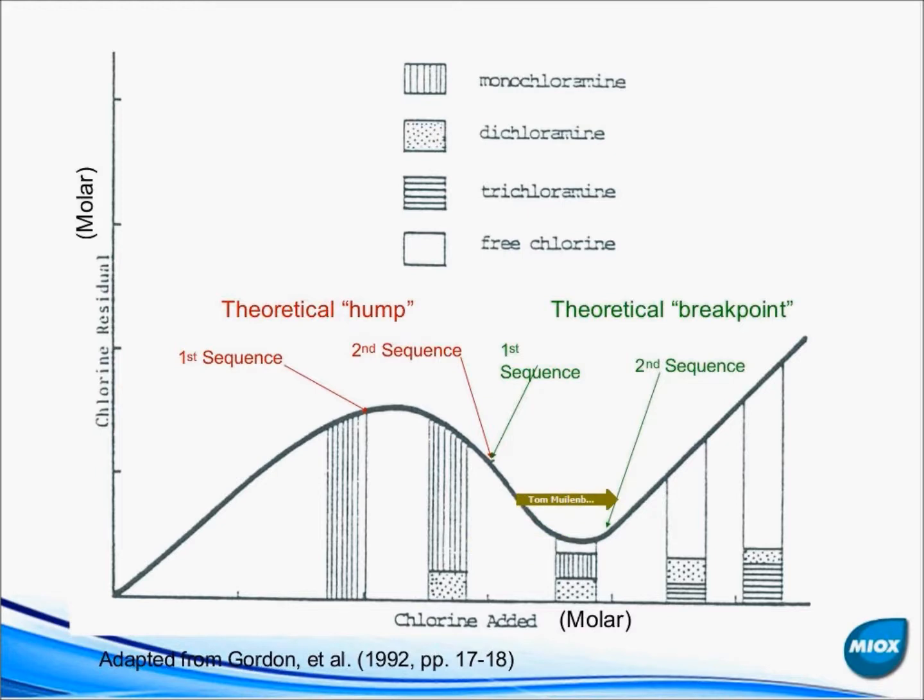And so this is where you've reacted all of your chlorine. So the beginning of this curve is where you begin to react. You start to really react, or I should say you're just prior to reacting, at this upslope. You begin to react at the peak, and then you start converting portions of your ammonia over. And then finally, down at the bottom, you've gotten as good as you can get with your ammonia conversion. And then after that point, you start carrying the chlorine residual.